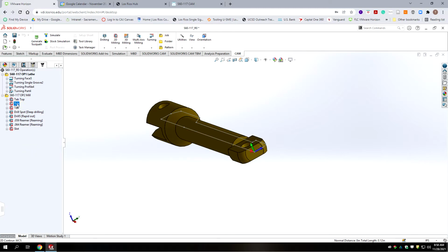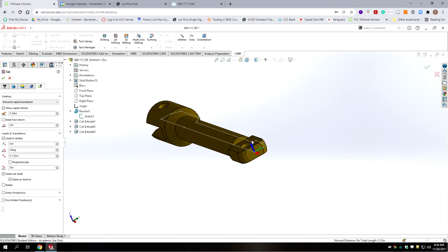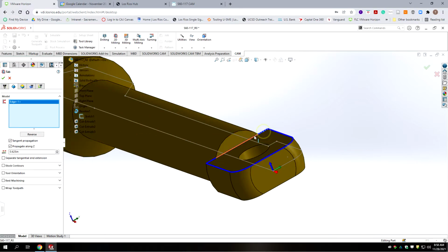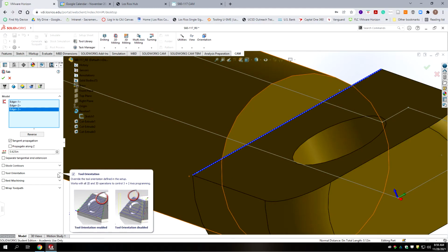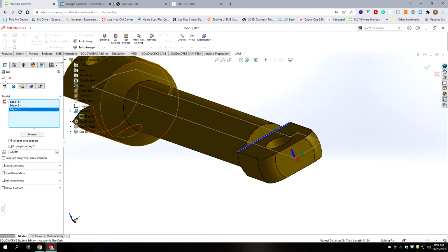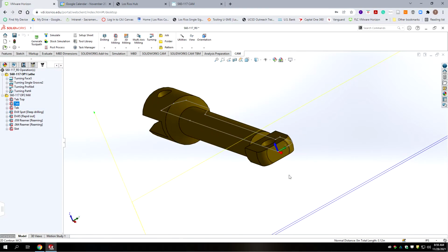Okay, we're going to go to the next one, and all we should have to do is go to the geometry tab and select our individual lines, deselect propagate along Z, so that we're not getting the entire chain, we're just getting those elements I selected. Okay, we're going to zoom out, and we should be able to accept those at default. So this should be our roughing cut. It's cutting below the tab.